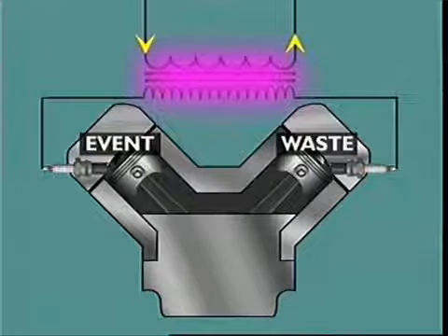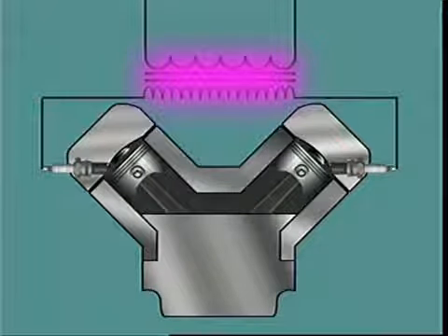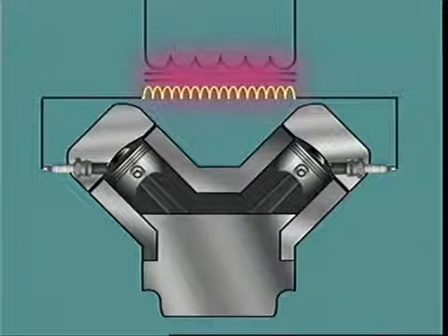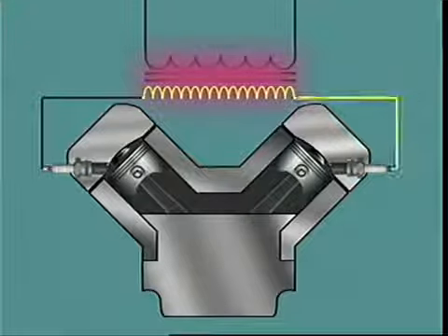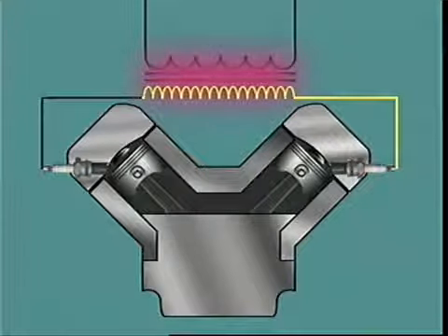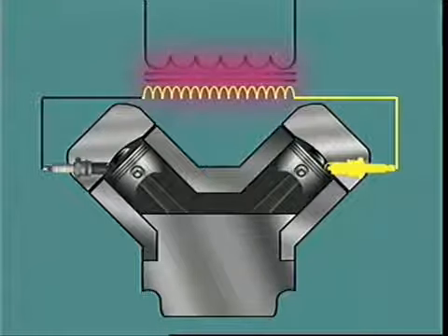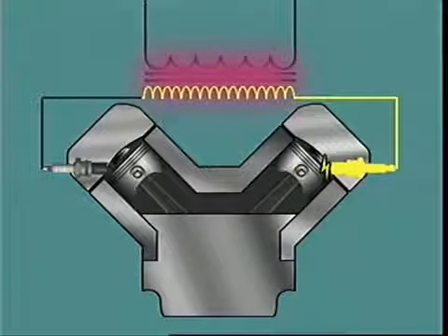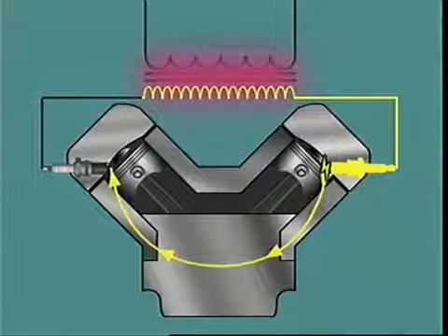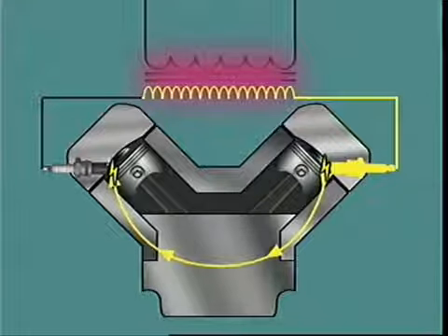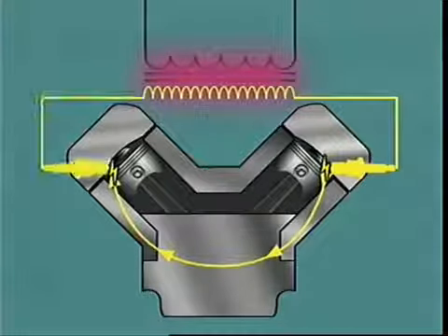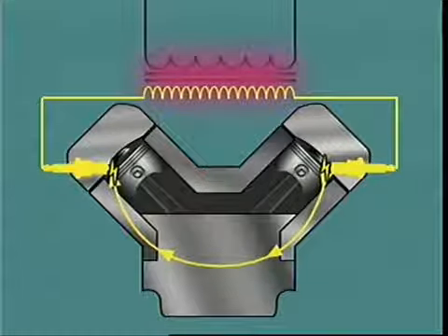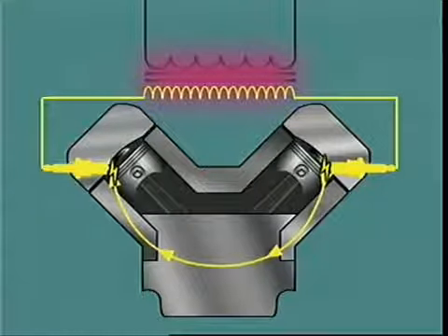is the waste cylinder. When the high tension voltage is induced in the secondary winding, the secondary circuit is completed by current flowing through the high tension lead to the center electrode on one spark plug, bridging the gap and creating a spark in that cylinder, traveling through the cylinder block, bridging the spark plug gap in the companion cylinder, and flowing back through that high tension lead to its starting point.